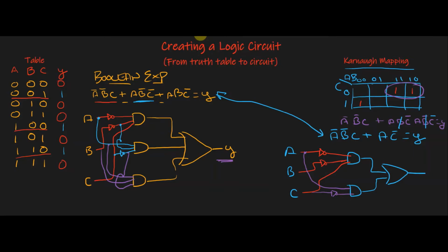Now, if I put a 0, 0, 1, I'll get a 1. If I put a 1, 0, 0, I'll get a 1. And likewise, a 1, 1, 0 will give me a 1. Any other configuration in this table will give me a 0, which of course won't satisfy the requirement to give me a 1.